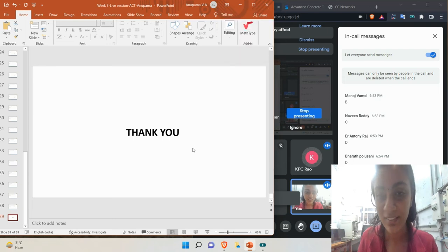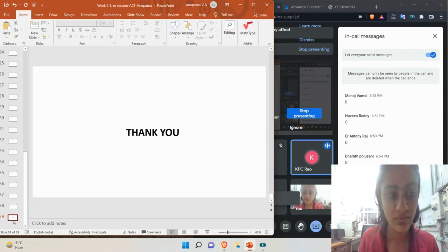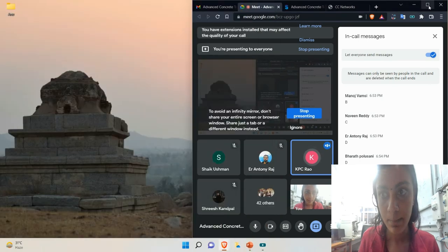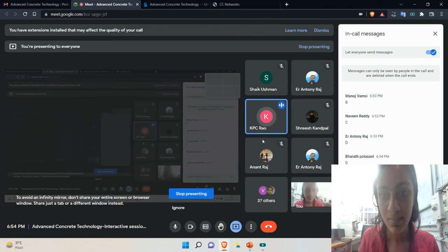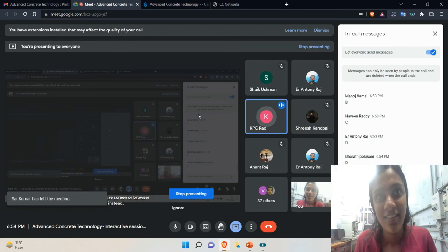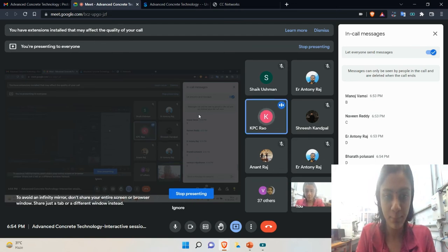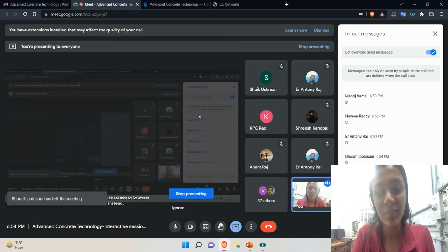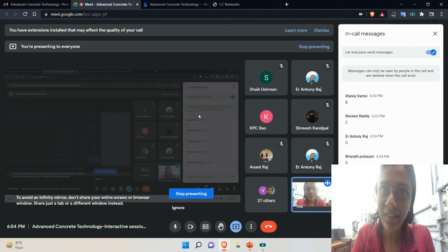I have a small doubt, ma'am. In the previous session, one of the participants had asked a doubt regarding the compressive strength of mortar. I could understand that we generally test the compressive strength of a cube, that is concrete. But what was the discussion about mortar and cement test? Because compressive strength is always related to the 150 cube that we use for the concrete test. It needn't always be on site, but in research facilities, we generally go for cement mortar cubes.